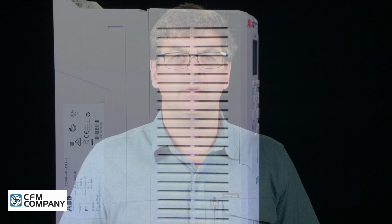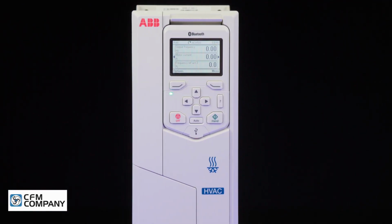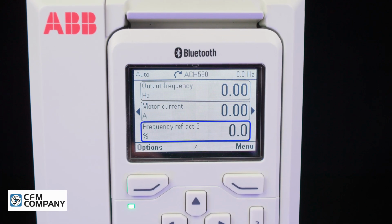In this video, you will learn how to program the ABB ACH580 drive for start, stop, and frequency reference control over serial communications. You will also learn how to change the third line of the display to show the frequency reference using percentage.